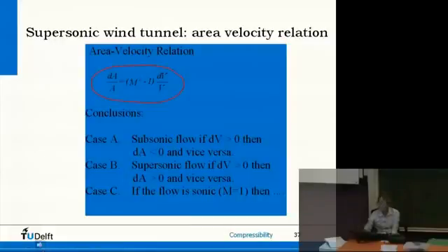Larger than 0. Positive. Perfect. So for supersonic flow, it's entirely the opposite. If my dA is positive, so my area increases, then my change in area has a positive sign. So this one's positive, this one was positive, then dV is positive too. So then, for supersonic flow,